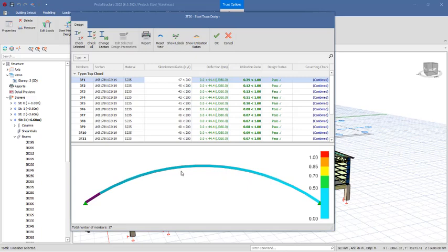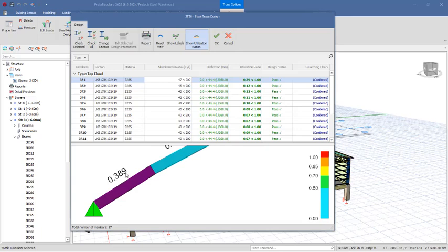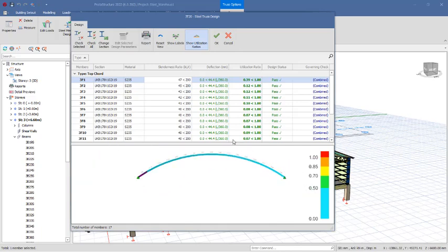curve sections, you can just click on show U ratio, and then you see all of the U ratio right there. You can see this one, 0.389, is found here, approximately 0.39, presented in 2 decimal places. So you're having it just like that. The same thing is applicable to every other provision. So this has passed design successfully.